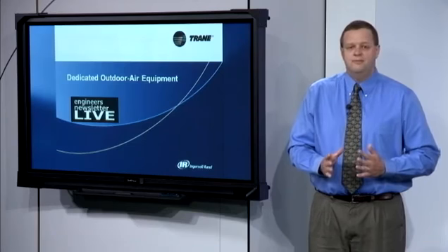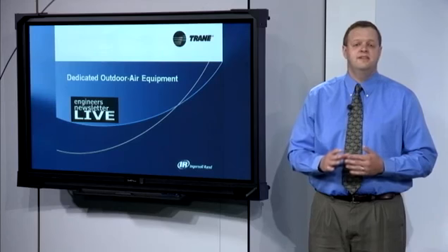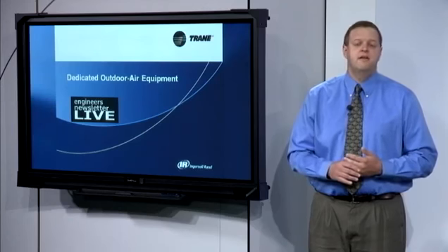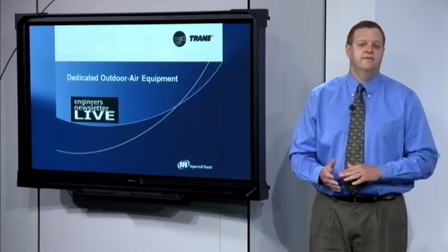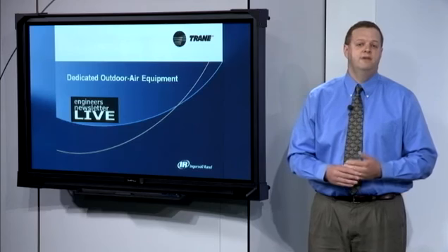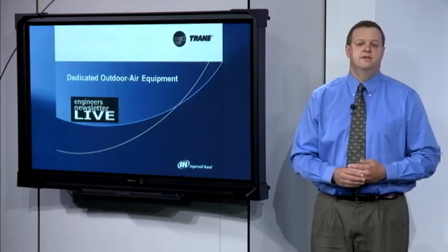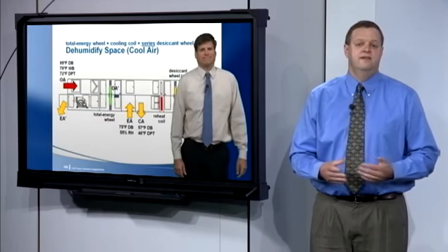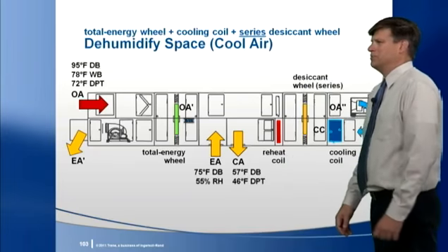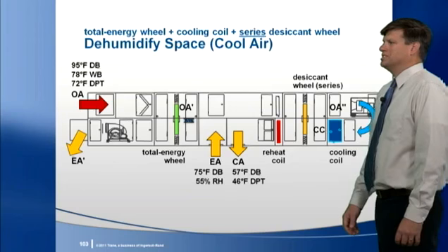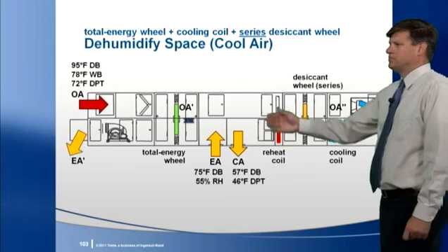Air that leaks out of the building due to positive pressurization and air leaving through local exhaust fans decreases the exhaust airflow coming back to the unit. And if demand control ventilation is used to reduce intake airflow, the central exhaust airflow must also be reduced to avoid negative building pressure. For some applications, there may be little or no centralized exhaust airflow to regenerate the desiccant, which renders it ineffective. For that reason, a better arrangement might be to configure the desiccant wheel in series to minimize this risk. Here, the regeneration side of the desiccant wheel is located in the outdoor airstream, upstream of the cooling coil.